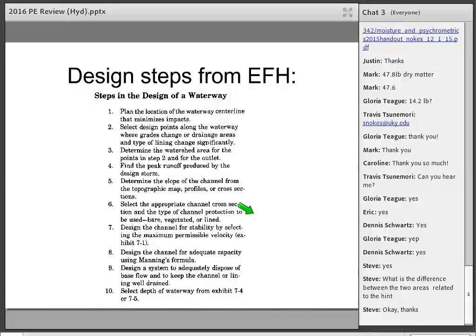Usually you go for a parabolic channel because the contractors can put a straight segmented channel out there with the equipment that they use, and as flow goes through it, it naturally goes to a parabolic channel. You look at the soils you're dealing with and the grass that you're going to plant so that you can get the maximum permissible velocity, which would be when the grass is mowed.